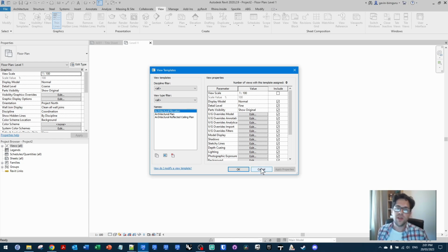Now, the really great thing about this tool is you can copy lots of different things that are very hard to copy selectively using this method. For example, view types, wall types, ceiling types, floor types, all types of things. It's pretty cool how many things are able to work this way. Not everything can be copied in such a way, but usually if you can get that object with its ID to be added to a list like we did, most of the time you can copy those elements across.